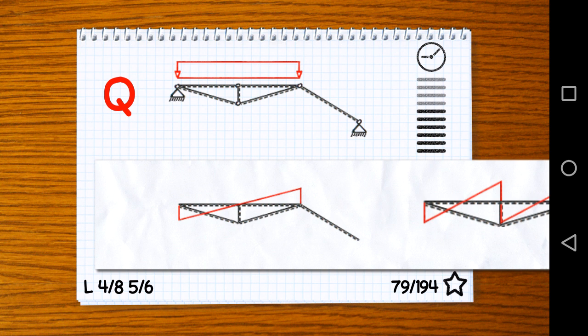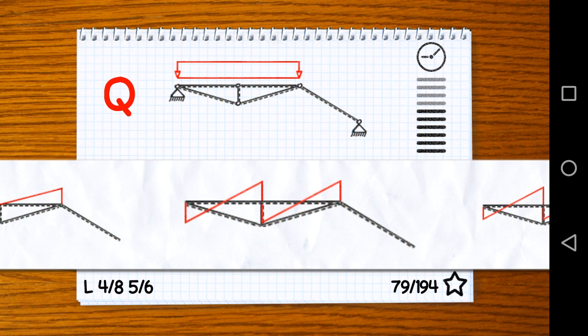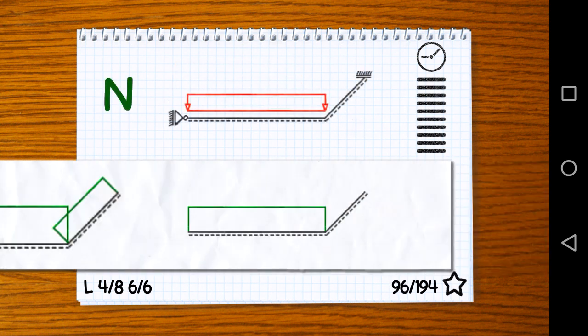For each element, we're gonna have a negative shear force, then a linear distribution, so that it goes a linear variation, so it goes to the positive value, and then for the next element, negative value, linear distribution, linear variation, so it goes to the positive value, and this right answer here is correct. The way it was drawn in the left part is wrong.